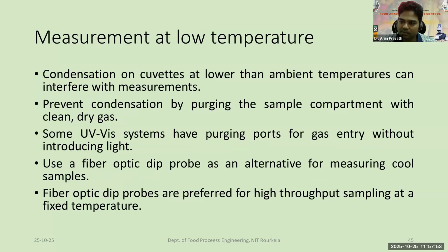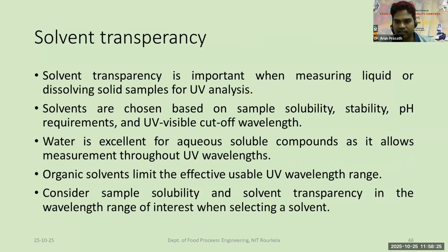There are some analyses where we may go for low temperature, especially when you are dealing with volatile components. When you are going for this low temperature analysis, we should definitely take more care to prevent condensation by purging the sample compartment with clean and dry gases. Some UV visible systems have a purging port for the gas to enter before introducing the light, to avoid condensation on the surface. And then the solvent transparency.